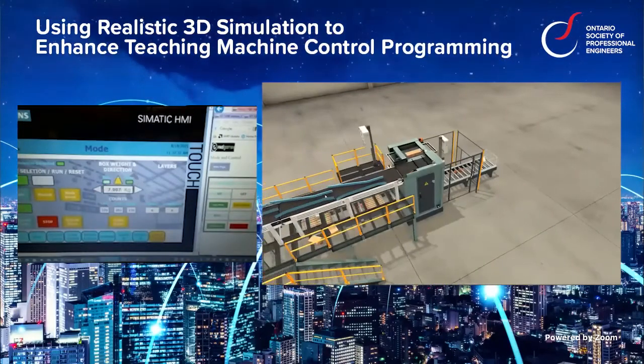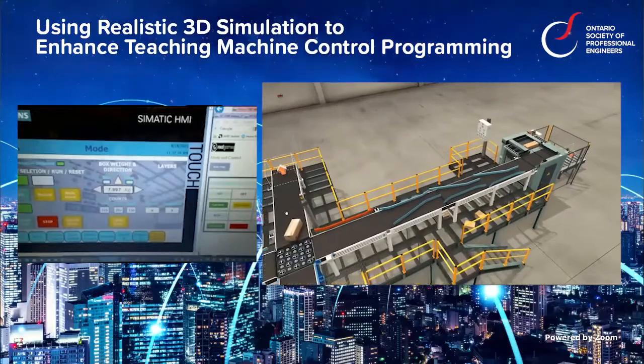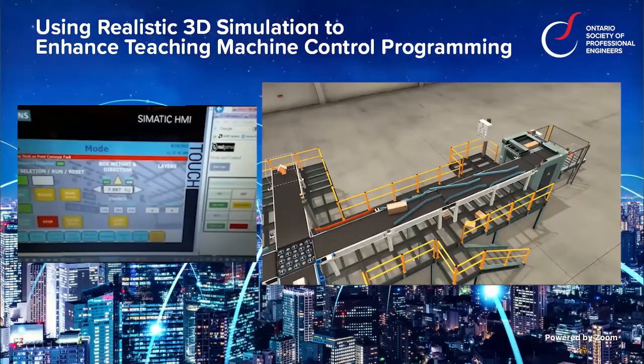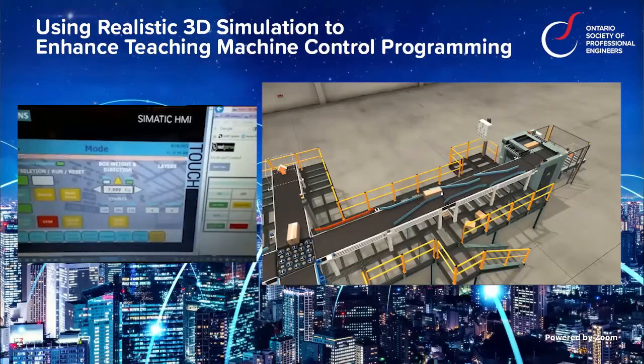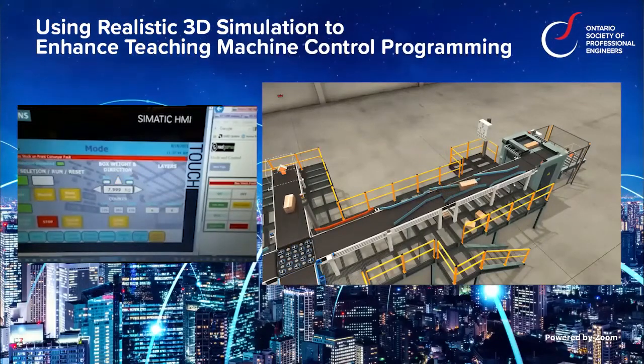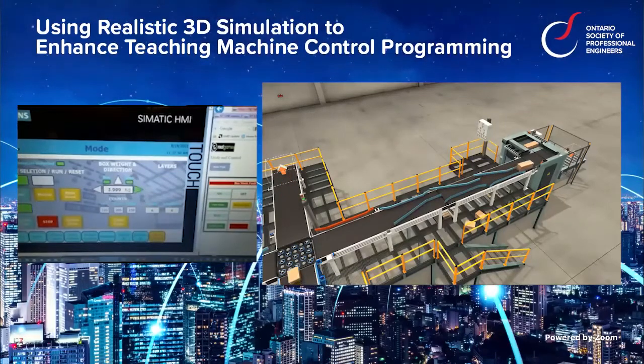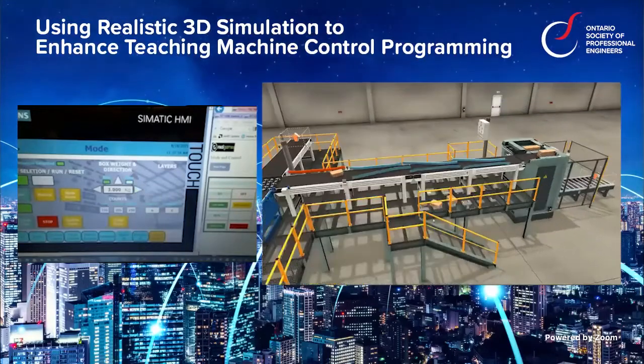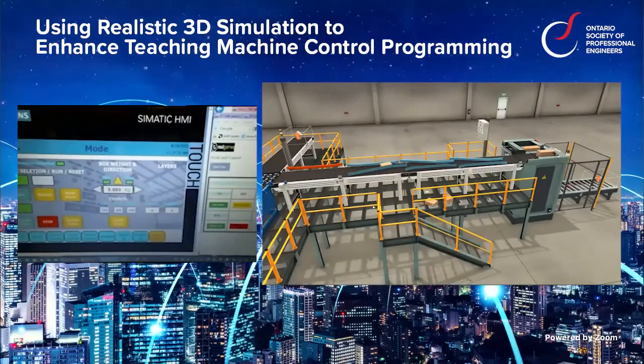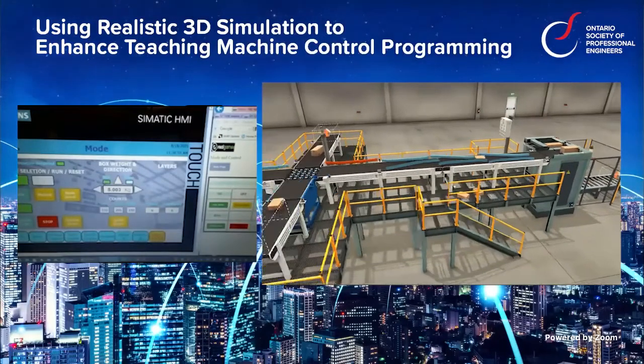Or I could create a jam up. Like grab this box and put it in here. Right now I have the wrong box down the conveyor. It's actually going to jam the system up somewhere along the line. Maybe jam up the pusher if it gets all the way through, and you'll see a fault show up on the HMI later. So, something that a real operator could accidentally do, put the box down the wrong conveyor. So it makes it a very nice, real simulation.